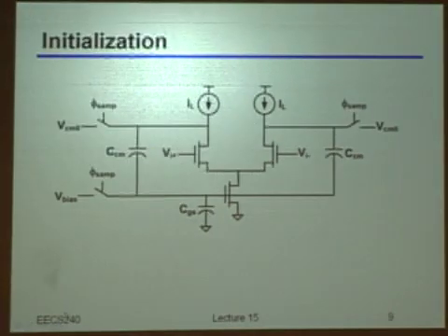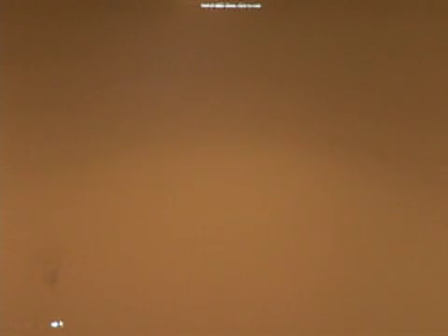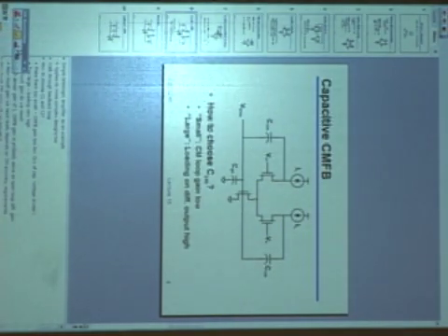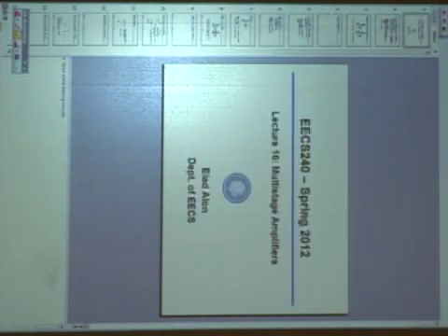You may want to also check the stability of the loop, and possibly run a transient analysis to see if, when you have a step in VDD, you can still guarantee your stability. So not only the phase margin is important there, but also some transient behavior.